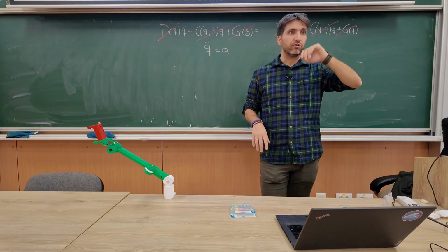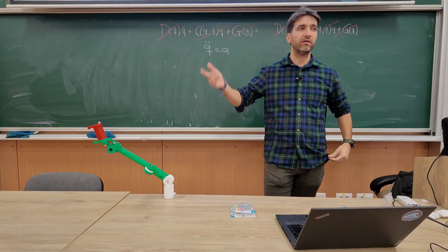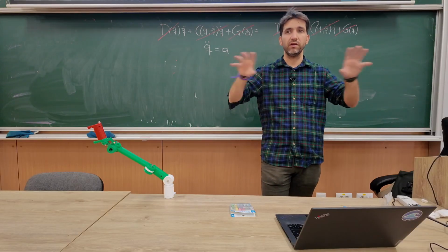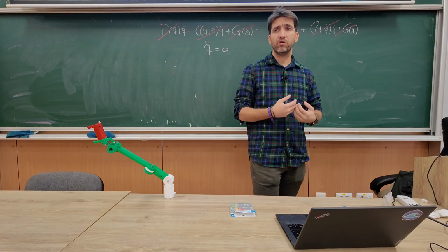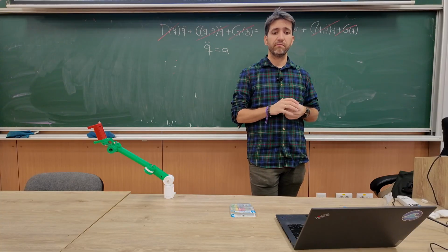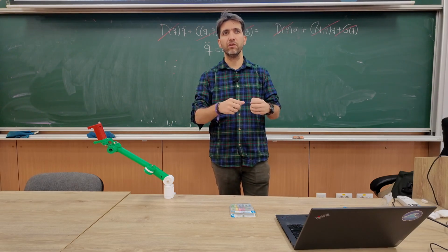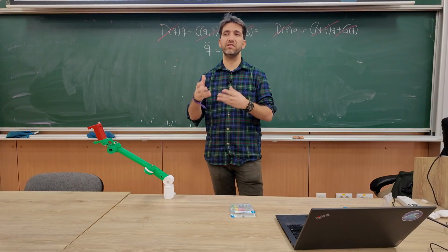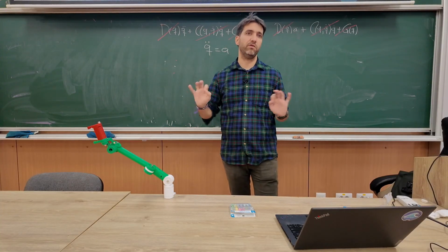Of course, we can do other approaches, as you said earlier, right? Any MIMO controller. The whole point here is this feedback linearization, like how can I get from this nonlinear system into a linear system, right? Again, this works as long as the modeling is correct. And you will try that in the lab. In the lab, we know exactly the model because it's in simulation, but you will introduce on purpose mistakes in the modeling, and you will see that the controller basically starts misbehaving. While, when the model is perfect, the controller is perfect as well.